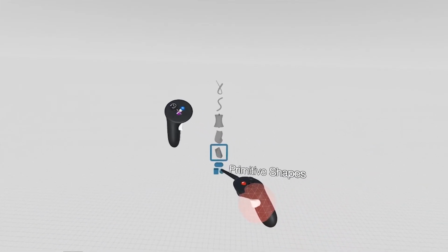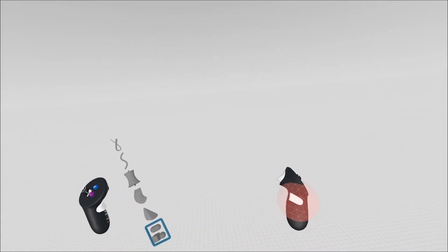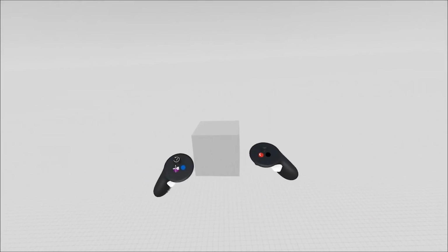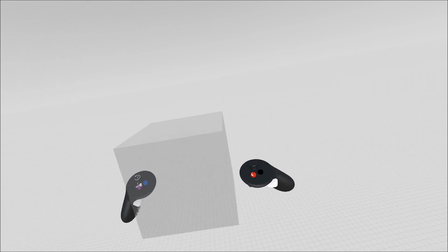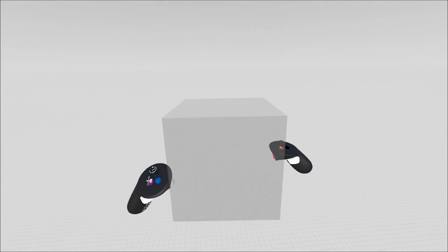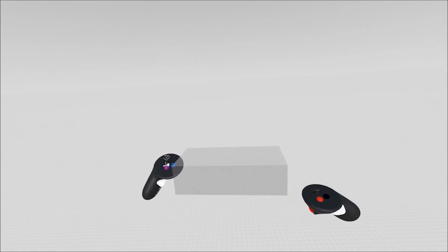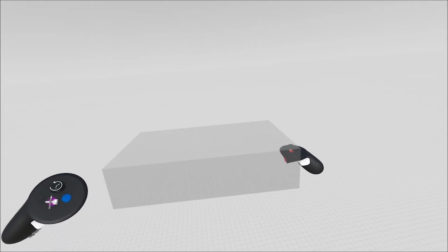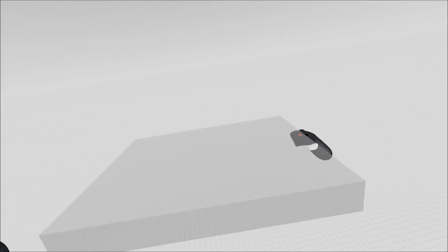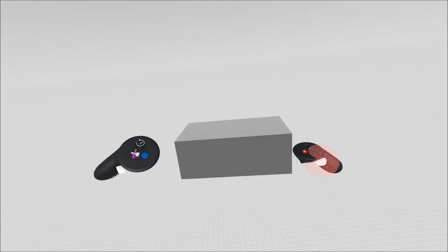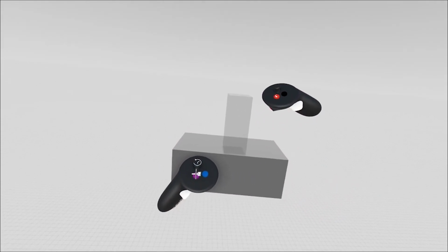We're now going to look at the primitives. The primitives are another two-handed gesture. This time pull the trigger finger first on the drawing hand. This will give you a consistent cube of a consistent ratio. By pulling the trigger on the non-drawing hand, you can then augment the shape using the hypotenuse. So as you move your hands diagonally across, you can influence the shape of the primitive. And once you release, the shape then is solidified in your sketch.